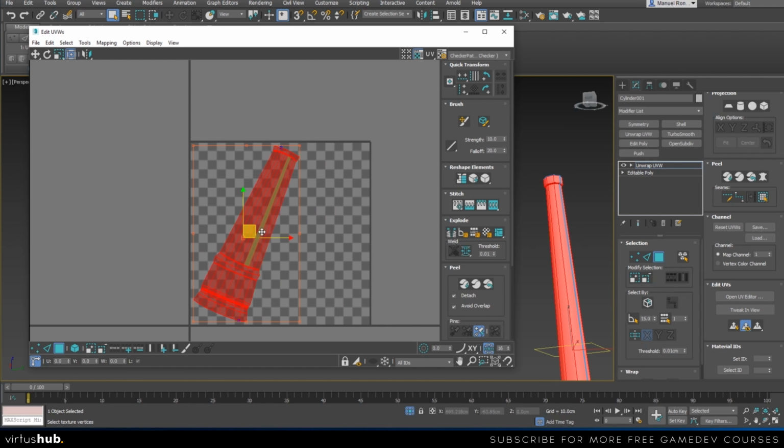One thing that you'll see me do in this tutorial is I don't like having oblique assets because this can occupy more space than what we really needed to occupy. So usually I like to keep my things vertical or horizontal. The other reason is because if I'm projecting a specific texture, let's say a sticker or a decal, it's going to be easier if it has a vertical or horizontal orientation than if it is oblique.